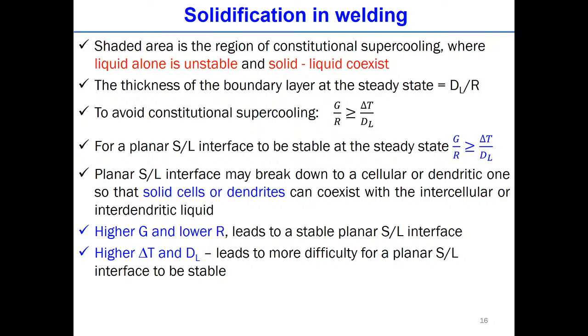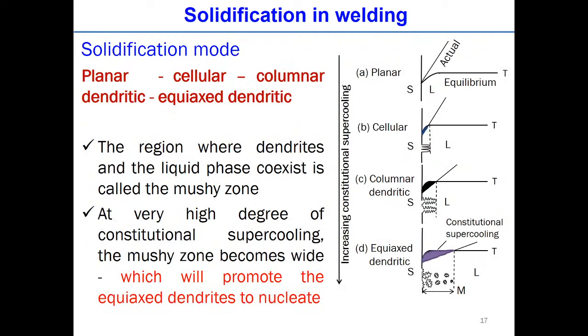We have given one particular problem in the assignment on how we can relate it to this. Here you can assume there is a boundary layer in front of the solid-liquid interface. We can simply estimate the thickness of that boundary layer if you know the diffusion coefficient of the particular material, and R is the rate of solidification. Accordingly, we can estimate the value of the boundary layer thickness. And we have also explained the dimensions, what the dimension should be. So this we have already explained.